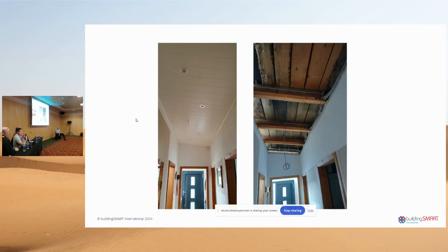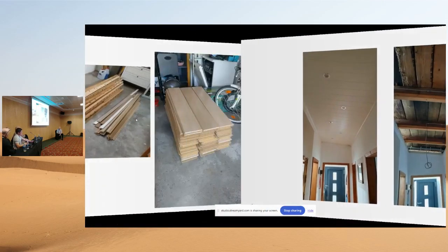It should release humidity, but not at the same time be airtight. So it's an intelligent membrane. If you have a PE sheet, in that case, it will not dry out with time in winter. So that was a main reason for this. So make it airtight, but ventilate right. Absolutely. Yeah. That's exactly the point.